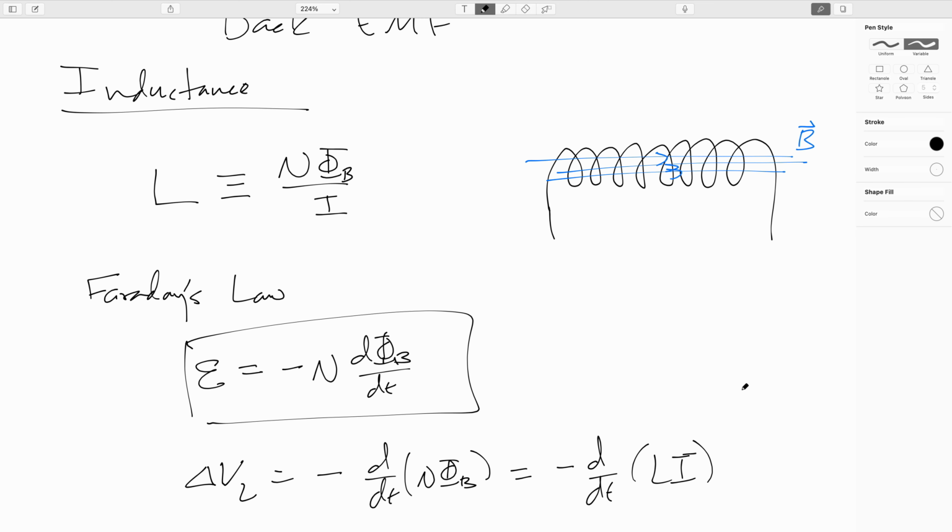Well, that's going to try to create a huge time rate of change of magnetic flux through the inductor. So you'll wind up getting a substantially large back EMF. So this will have the effect of damping down the increase in current. So instead of it being nearly instant, which might cause damage to devices or something like that, it will indeed ramp up a little more slowly.